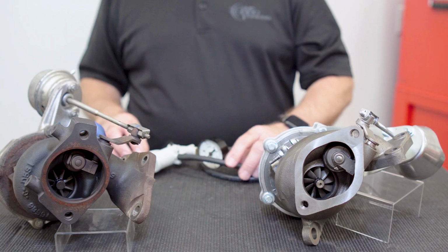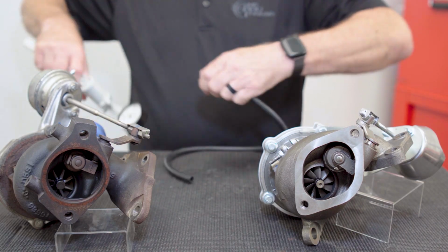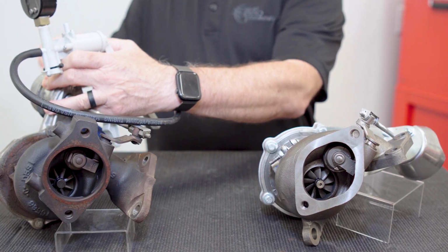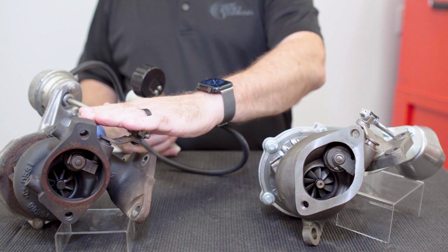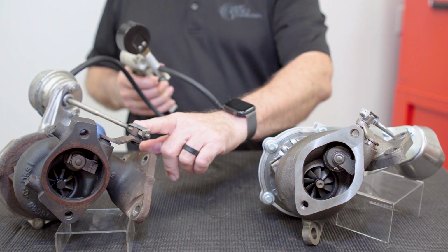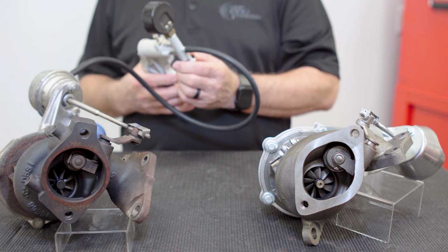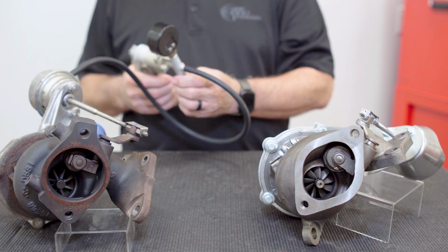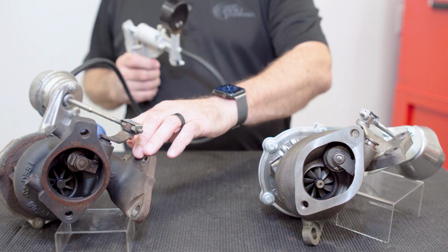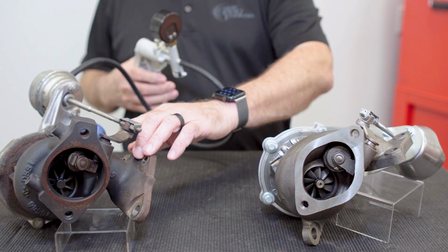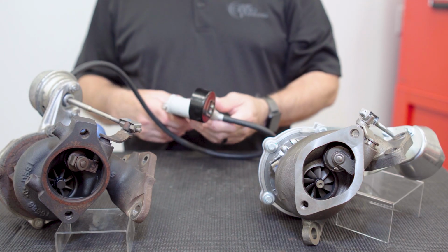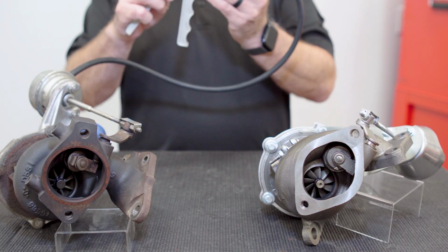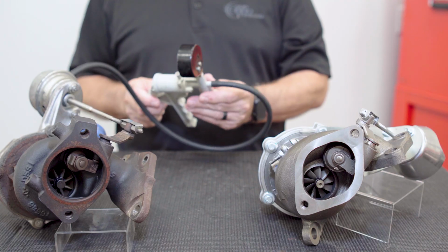All right, now on a vacuum actuated, it's just the same thing in reverse, okay? We're just taking vacuum, we're applying it to the wastegate actuator because we have boost, we don't want boost, and we apply vacuum after we close the vacuum pump. There's our actuator moving. Easy peasy. Now this is on vehicles where you can fairly easily access this, again, using your Mighty Vac vacuum pump. Very easy and simple.